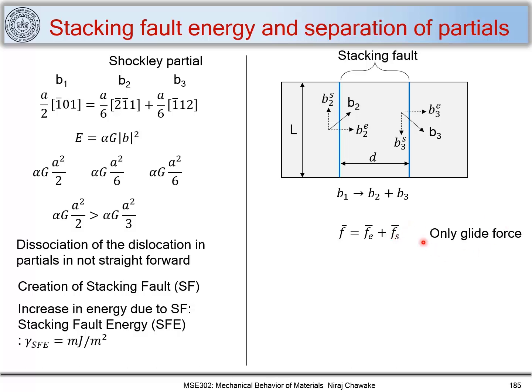We are considering only glide force, not climb force. Let F be the force per unit length of the dislocation. With dislocation length L, the total force exerted is FL. This will be balanced because the stacking fault creates an energy, while the edge components repel each other.